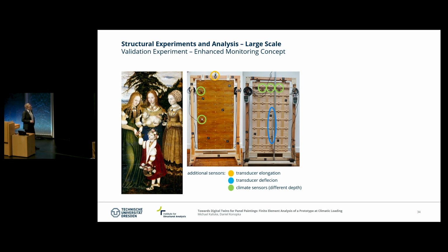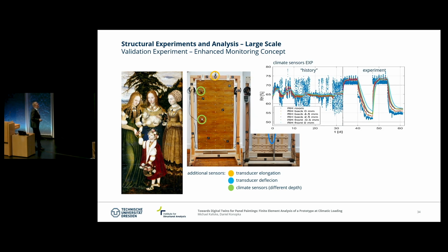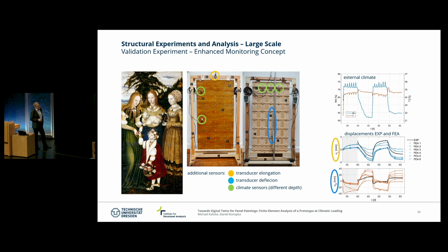So additionally, we put some climate sensors in different depths of our replica. We have a sensor for the deflection and for the elongation. That's what we recorded, as well as the climate, or the moisture content in the construction. And out of that, we took, for example, the external climate, which was measured and which we took then here for the loading case in our simulation as well.